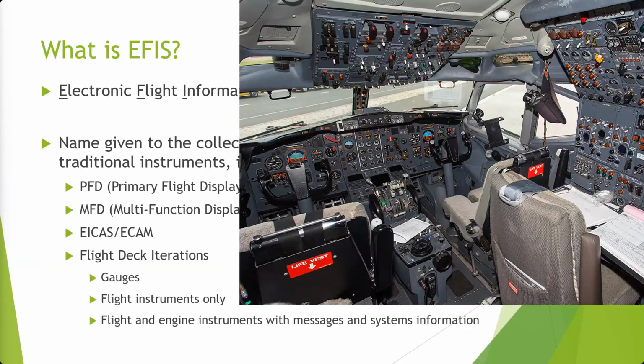You know, there might be a few digital gauges. These were like the tank quantity gauges. They originally were analog, but then they put a little digital gauge that did the exact same thing, just so you could see numbers and get a little bit more accurate reading rather than trying to read a scale. But electrical, everything there is analog. Down here, hydraulic pressures are analog. If we could look further over, we could see things like pneumatic pressures are analog and other stuff like that.